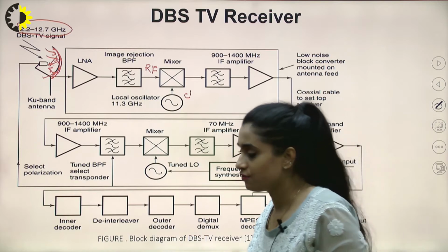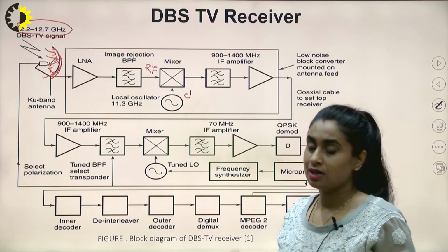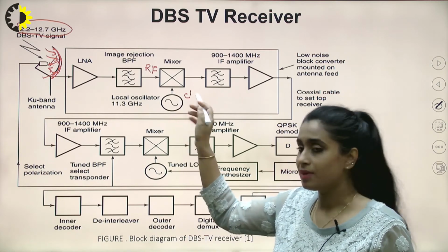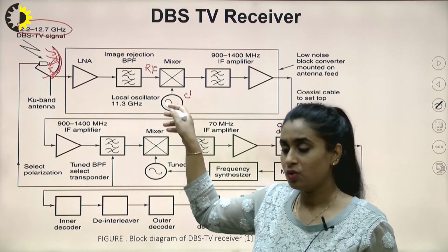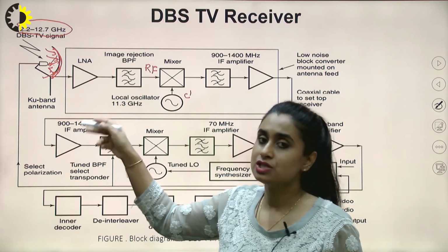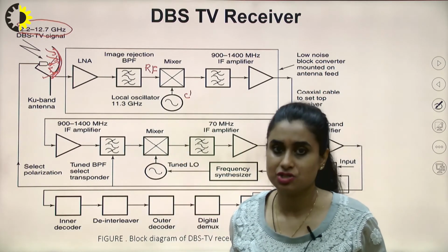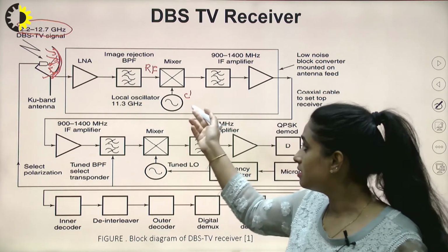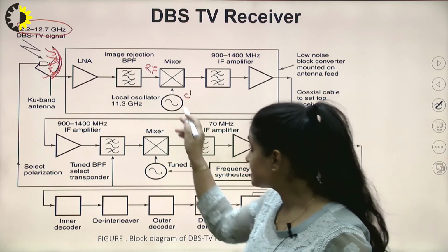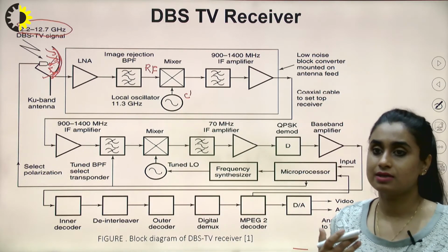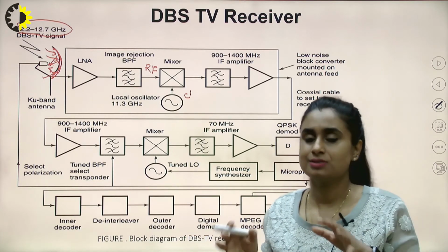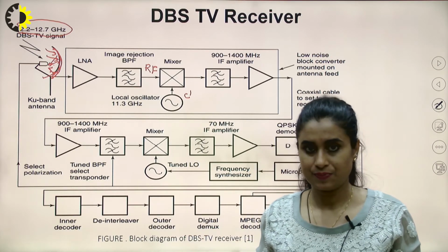In the case of coherent detection, if we study communication in detail, this oscillator must generate a wave which is coherent in phase and frequency with the carrier wave used at the transmitter for modulation. Here, the receiver and transmitter are geographically far apart, but we still have the information of that phase and frequency, and we generate it locally. That's why this oscillator is called a local oscillator.